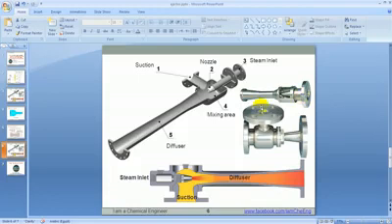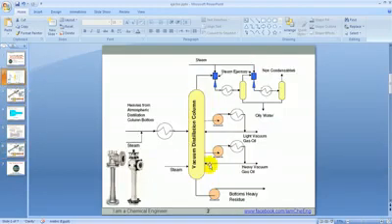As we saw from the continuity equation and the Bernoulli equation, that would result in very low pressure. So at this point, the pressure would be very low, even lower than our main system, which is the distillation column. So the pressure here would be lower than here, and the fluid would be driven from the column to our steam jet ejector. The system in our situation here is vacuum distillation. This is the main idea of reducing the pressure using a steam jet ejector.